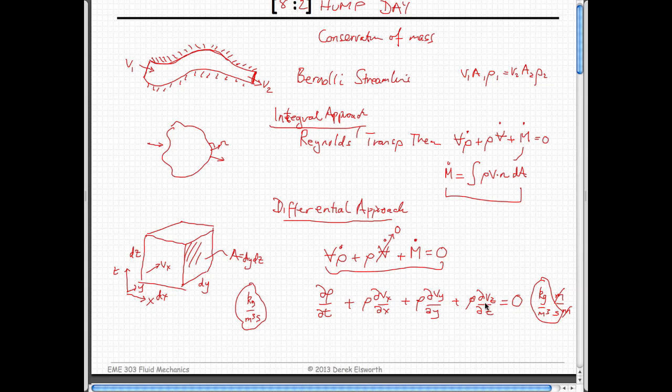And I won't do it here, but if you throw, for instance, Darcy's law into here, and you might not know what Darcy's law is, but that doesn't matter for now. It's just a way of linking a change in pressure as you go across the system as a function of a permeability and a viscosity. If you throw this into these expressions, you end up being able to get a single equation which is written in terms of pressure, the fluid pressure that you have in a porous medium or that you'd have in the air around a plane for that matter.